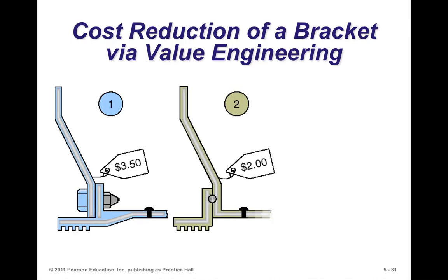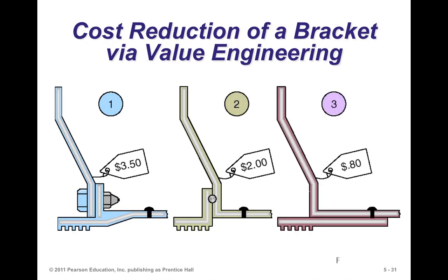So let's look at an example of how you could do value engineering. You want to really reduce the cost of producing an item. Take a look at this. So you're producing this and you have it made in these two parts and you bolt them here. So you got to pay for this bolt, and then of course you think of the shape, particularly the bottom one, and it looks a bit complicated. Now what if you did this? What if you welded the two parts here? You still get what you're more or less looking for. It's a bit cheaper, but you perhaps could do even better.